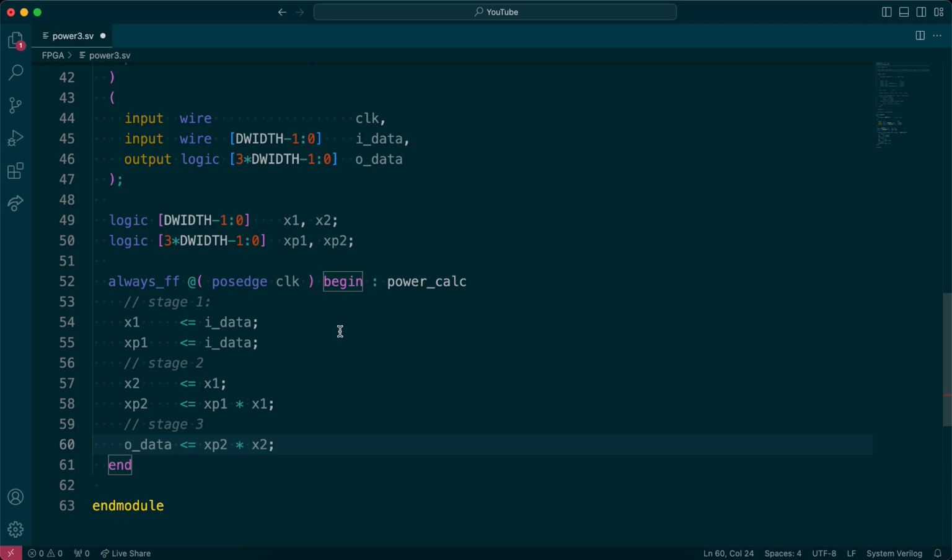And the other thing that I wanted to say is that the throughput performance has increased by a factor of 3 over the iterative implementation. And in general, when an algorithm requires n iterative loops, and when you unroll that, then the pipeline implementation can improve the performance in terms of the throughput by a factor of n. Okay, that's something to note.